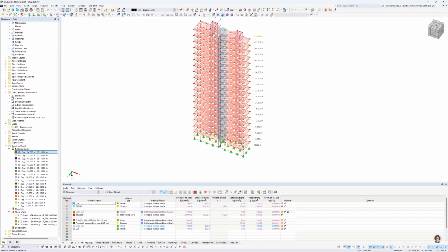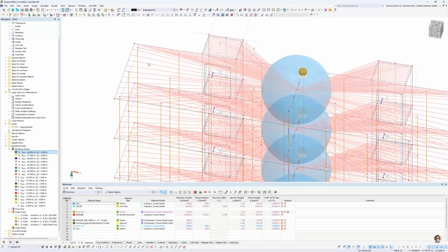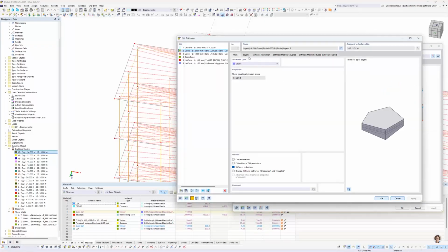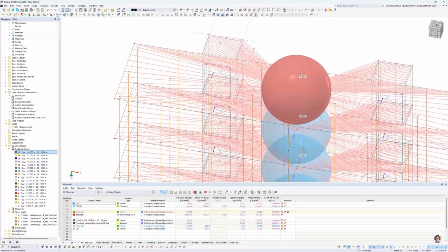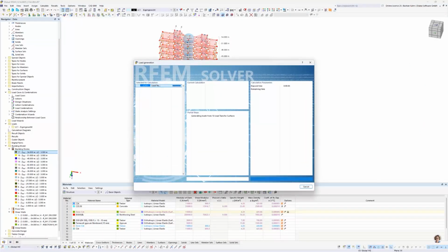Right? So the difference, I mentioned it already, from semi-rigid to rigid is that now it has a very high stiffness in the area. There's not any more the stiffness that is calculated here. Each FE element is connected to the mass center with a rigid member, which has hinges. And we can also calculate this and take a look.